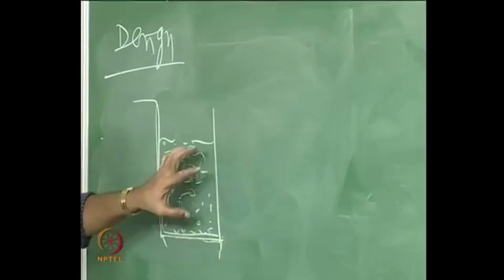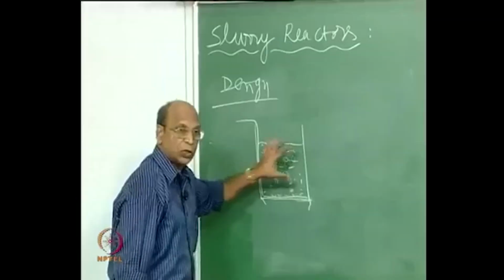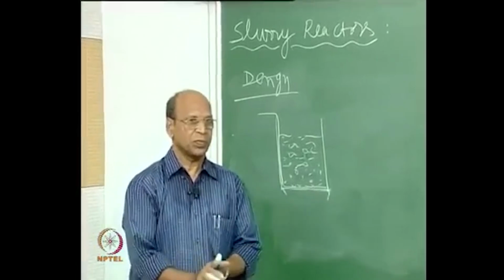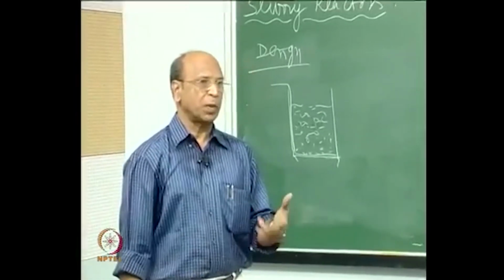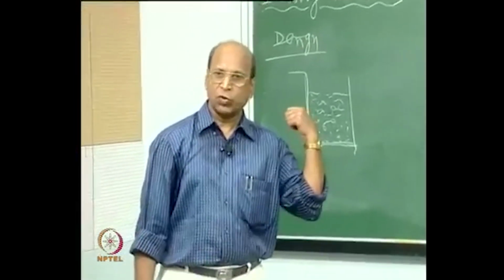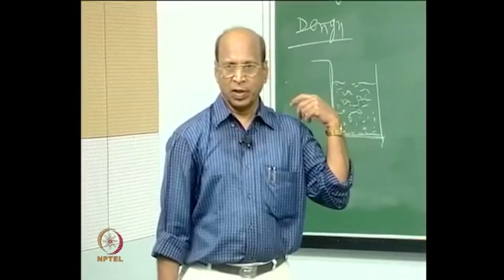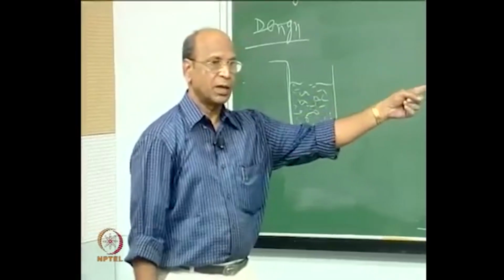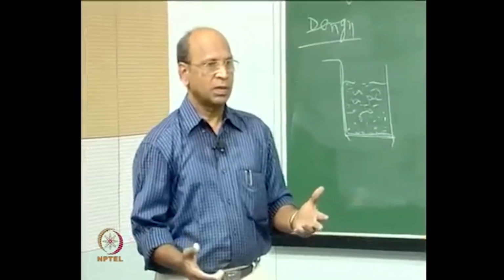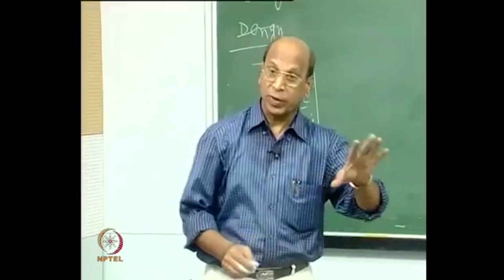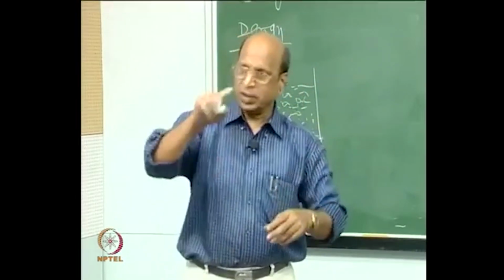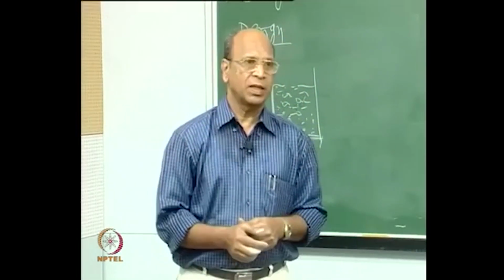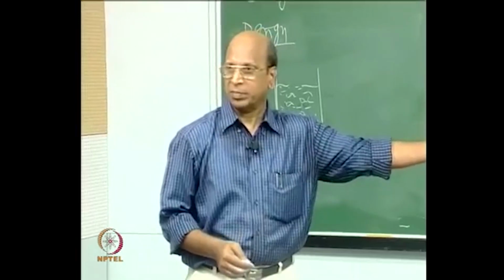Right. So, I am taking now that one thing is that we can also take based on the liquid phase, because we want to design now, right. So, your interesting phase may be liquid. If it is liquid, that is equivalent to a batch liquid, and you have the rate expression. What is the equation? t by C_A0 equals, it is liquid, integral 0 to X_A dX_A by minus r_A. This minus r_A is that.